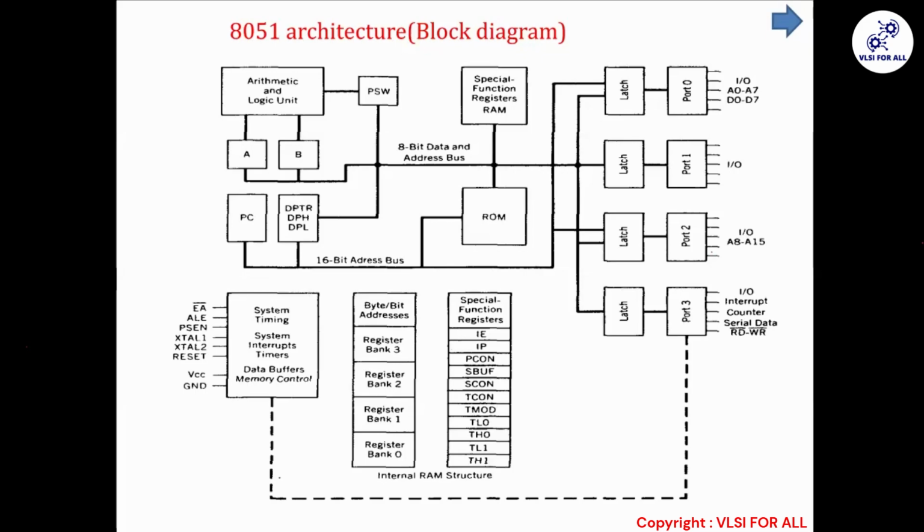It is a stack of 128 bytes, meaning 0 to 127. If you convert that 127 into hex, it will be 7F. So that is a stack starting from 00 going up to 7F. And above this 7F, what will it be? 80 to FF. Are you getting it? How much part is remaining?